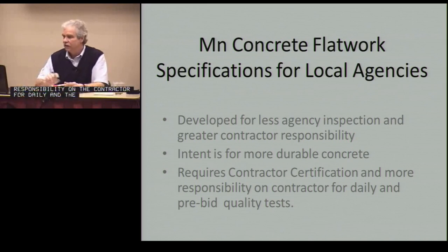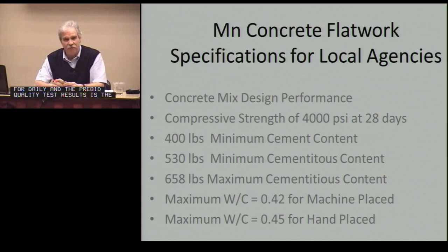The mix design is a performance mix. We're going to go with 4,000-pound concrete at 28 days, compressive strength. Most of the MnDOT mixes are A mixes, and they run at 3,900 PSI strength. So we made this one 4,000, so it'll be different. So you know you're into a different spec than the normal Minnesota DOT, which are anticipated strengths.